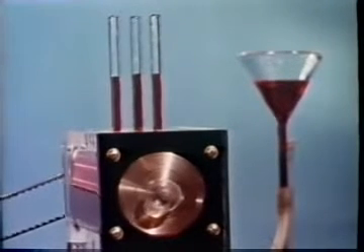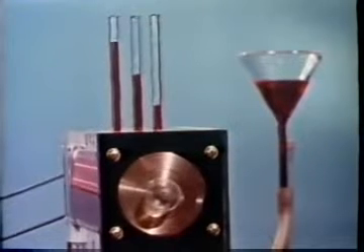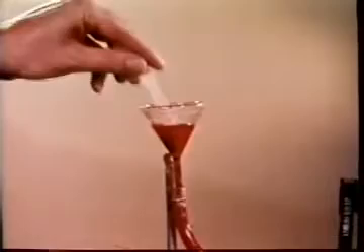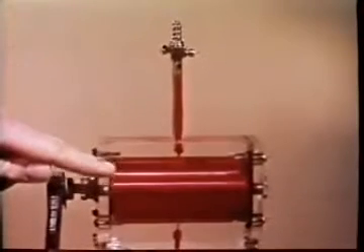Reversing the direction of rotation reverses the stresses and the pressure distribution. Very large pressure differences can result from greater eccentricities or speeds, or if the fluid is very viscous. In this case, the journal has been filled with syrup. By sealing the journal from the atmosphere, such a strong negative pressure is built up in the diverging section that cavitation bubbles appear. The bubbles get longer as the speed increases.